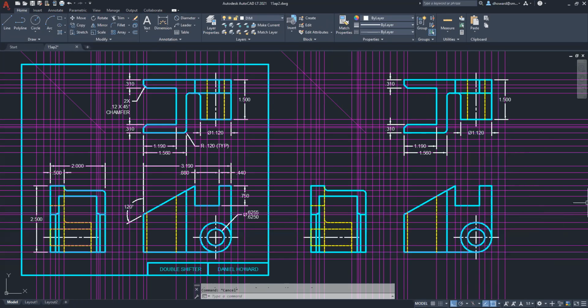That's how it's done. So to get that diameter symbol to show up, you're going to have to add it before you locate the dimension. So again, before you click its location, type M, enter, so that you can add that diameter symbol.